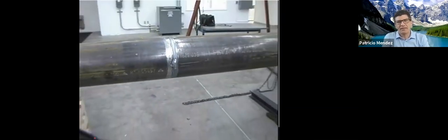So they say nothing about the tests, and in the pipeline industry, it doesn't matter how beautiful the weld is or how beautiful the grinding is, you have to test it and see how it goes. Knowing how difficult those tests are, I doubt that this is a ready product. And in addition, the tests are very much tailored for arc welding. So even if these were to perform well, it would be hard to qualify.